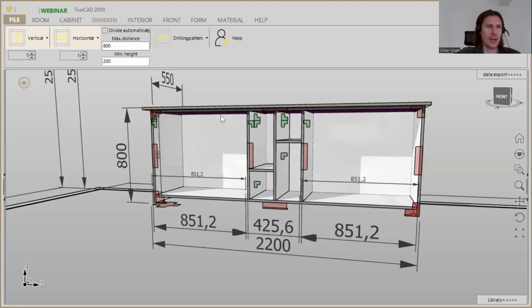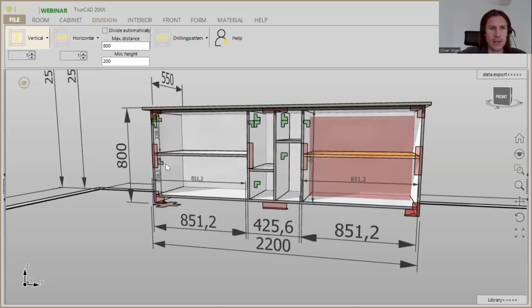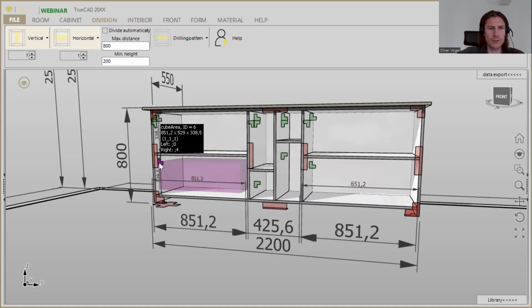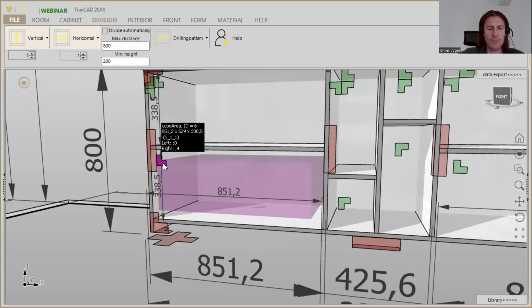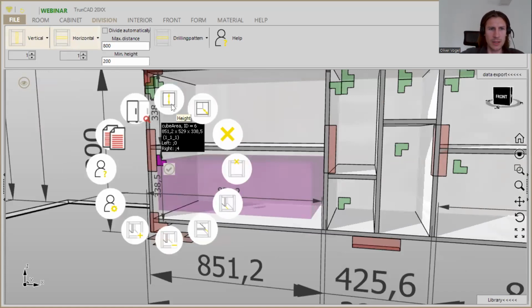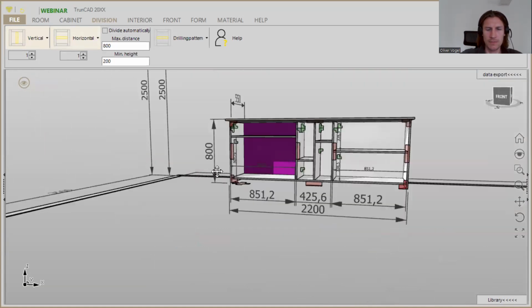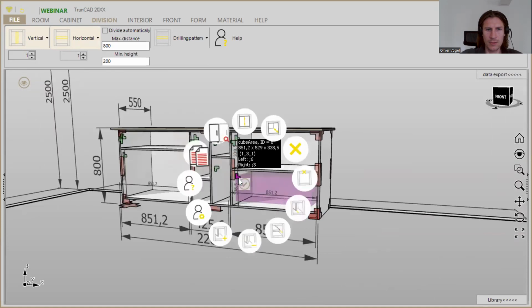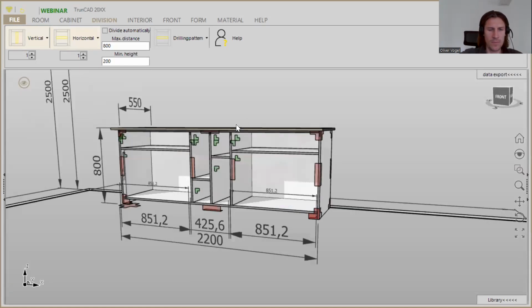So for the left and right side we have here one horizontal, and the areas are related in relation 1 to 3 to each other. That's why we go here on the smart click for the bottom area, click on the smart click, and here we change the height to 3. Then the relation is 1 to 3. So here the same. All right.